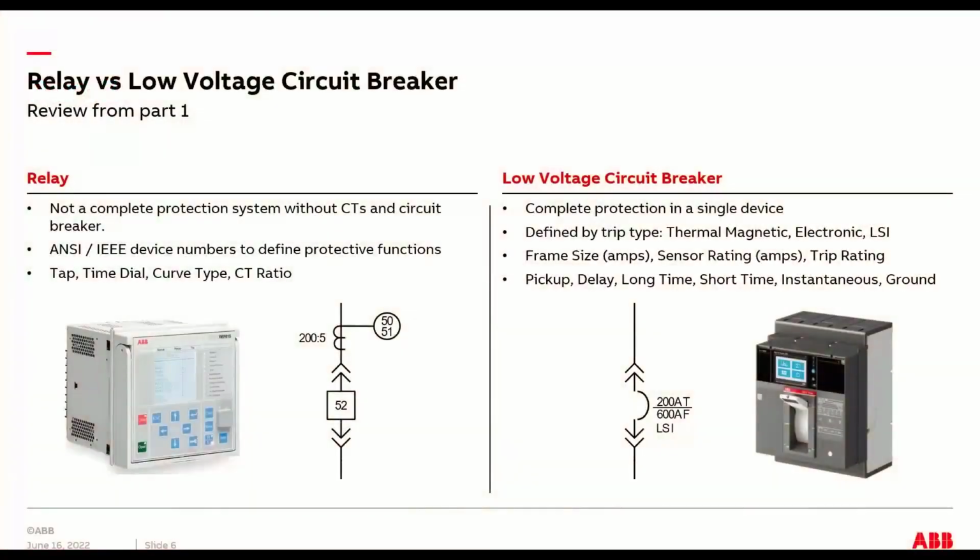So part two, just a quick review between the protective relay, medium voltage, high voltage protection versus low voltage. The relay itself is only a piece of a larger system, whereas the low voltage breaker is a single package with everything built into it. So it's the brains plus the switch. It's all been pre-engineered. You really only have to call out that one device, the low voltage breaker, and it's a complete system. Relay is not like that.